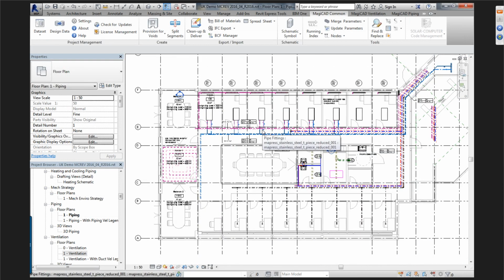that you can now update the data from the Revit model with Excel and apply formulas a lot easier than the Revit format, which is going into a schedule and trying to manipulate the data in Revit, which is quite tedious, because a lot of the functions you get in Excel as a spreadsheet are missing in Revit's own scheduling, such as even copy and paste doesn't exist in Revit schedules, so it can be a very tedious job. So that's a very quick way of updating a lot of your data.